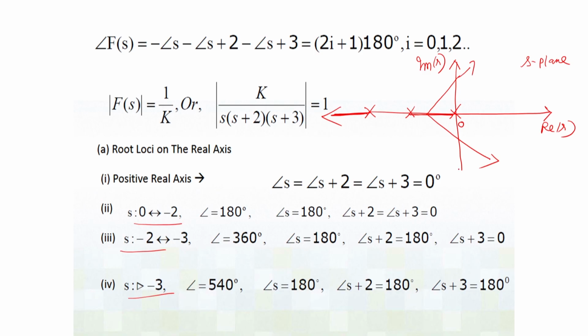So, that means the behavior of the poles will be that one pole from the open loop poles will go like this, one will go like this, then they are going to diverge and go to the right half plane, creating instability. These 2 poles will definitely create an unstable situation, and the third pole will go towards the left hand side. The more it goes towards the left hand side towards the 0 at infinity, the more it will be irrelevant and the system will become a second order system, but it would become an unstable second order system.